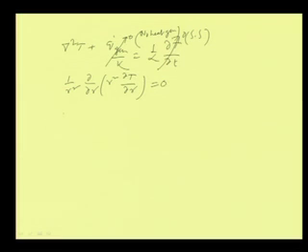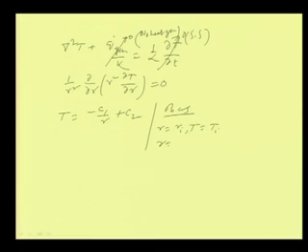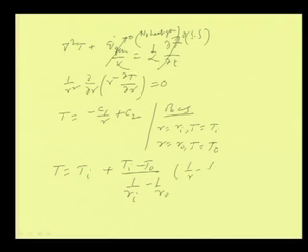From here, what we can write is T is equal to minus C 1 by r plus C 2, and if we put the boundary conditions here, at r is equal to r I, T is equal to T I, and at r is equal to r O, T is equal to T O. If you put the boundary conditions, then we come back to our temperature expression: T is equal to T I plus (T I minus T O) by (1 by r I minus 1 by r O) into (1 by r minus 1 by r I). So, this is the temperature profile in a spherical vessel.